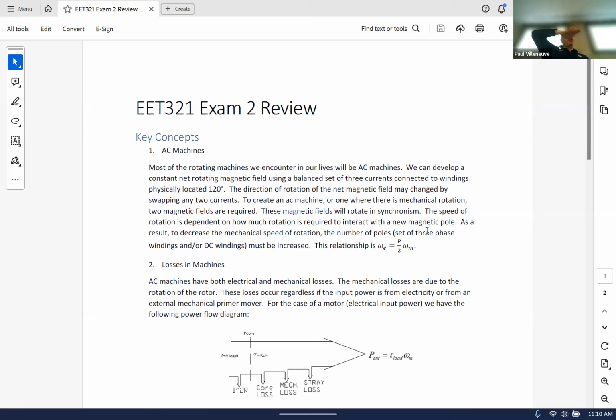And normally people think they flow along the surface. Most of the time they flow down. Anybody want to guess as to why electrons flow down before they head back? They're looking for the most electrically conductive point. Where do you think you're going to find the most electrically conductive point? Where it's moist and wet, right? So the deeper you go, there usually is a more consistent level of water.